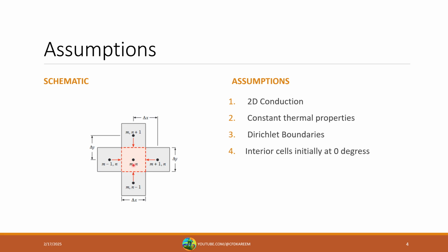For all of our internal node values, we're going to start by solving the value at that node by looking at the finite difference between all of our surrounding nodes. So we'll take the one to the north, south, east, and west, and use that to come up with an expression for each of those internal nodal points.